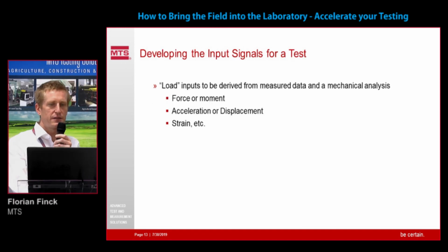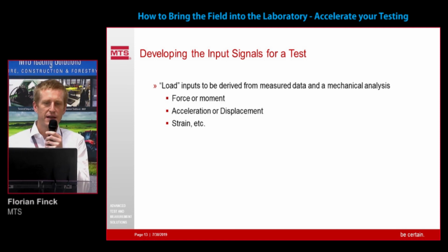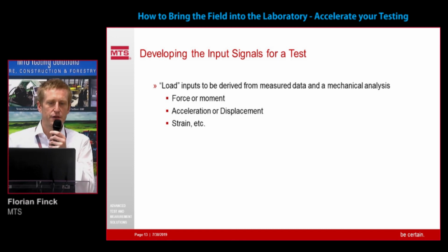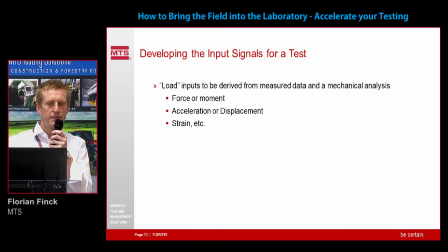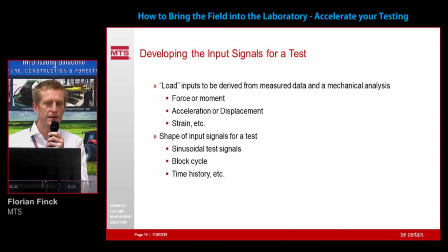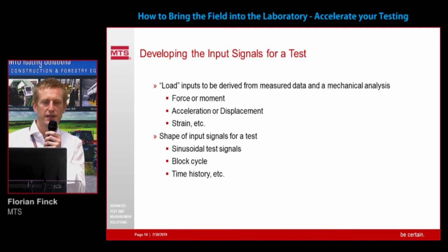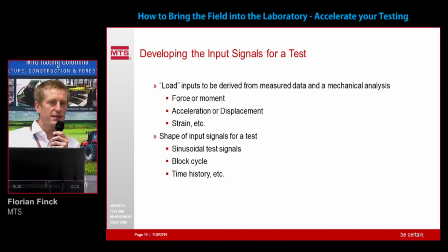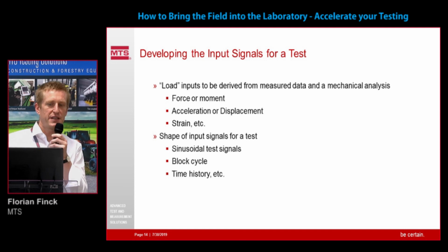So then it's about the input signals for a test. The loads that are derived from these measured data are forces or moments, accelerations or displacements, or strain signals. Most of these signals can be used to control your test system. And then the question is, what is the shape of these input signals? Is it a very simple sinusoidal test, where I can generate signals in an artificial way? Do I have some block cycles? Do I mix certain amplitudes? Or do I have time histories?